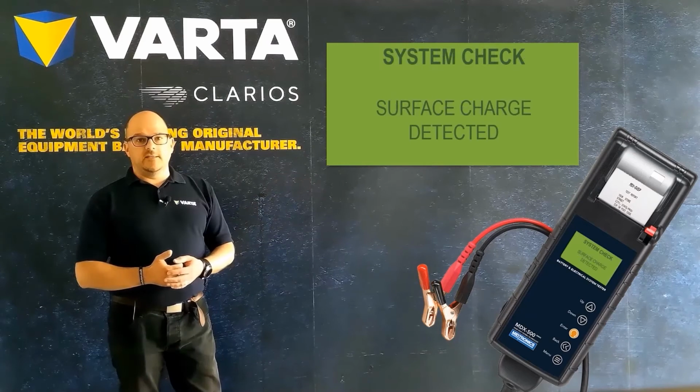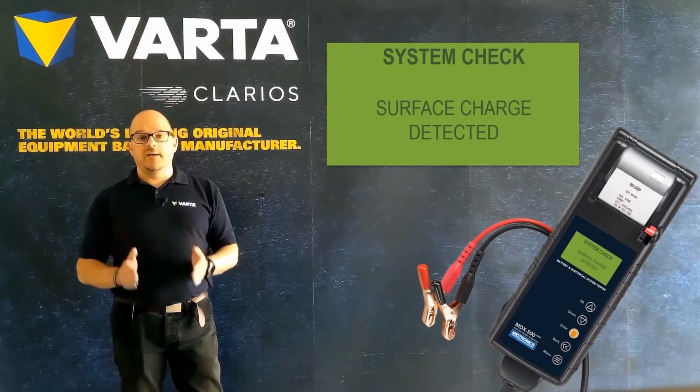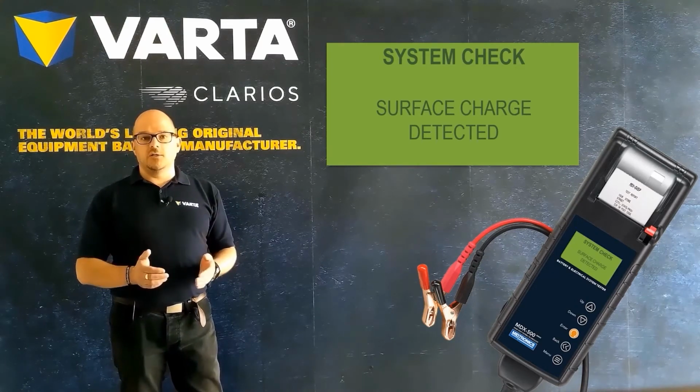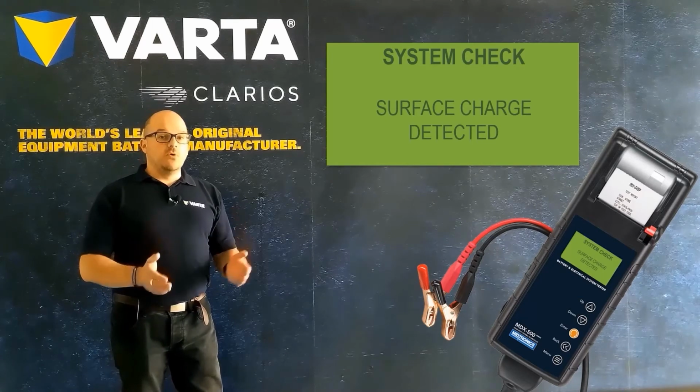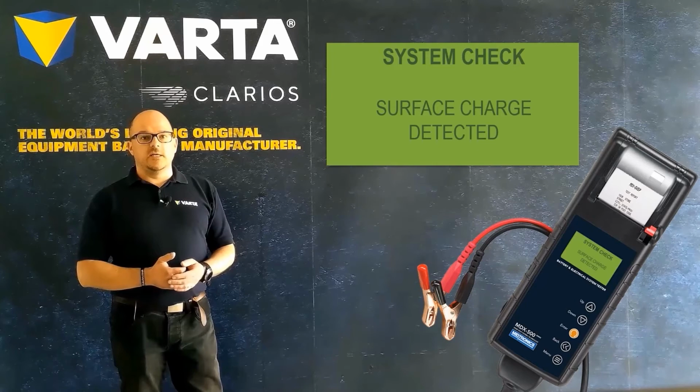Surface charge detected. This usually happens if the battery has just been recharged and not left to stand, or the car has just been driven for a distance and charged by the alternator. To remove the surface charge, turn on the headlights until the tester sees that the charge is gone.